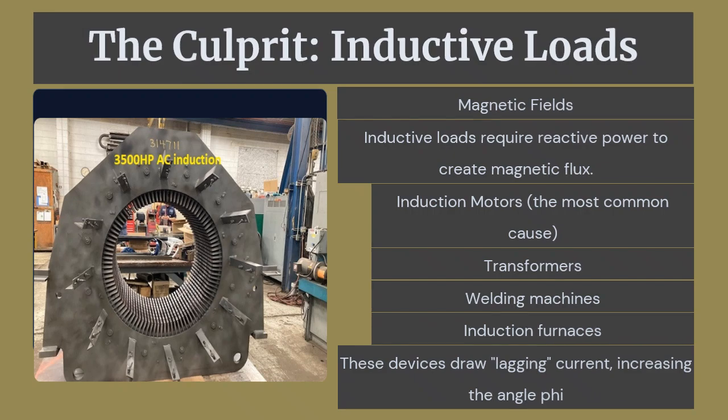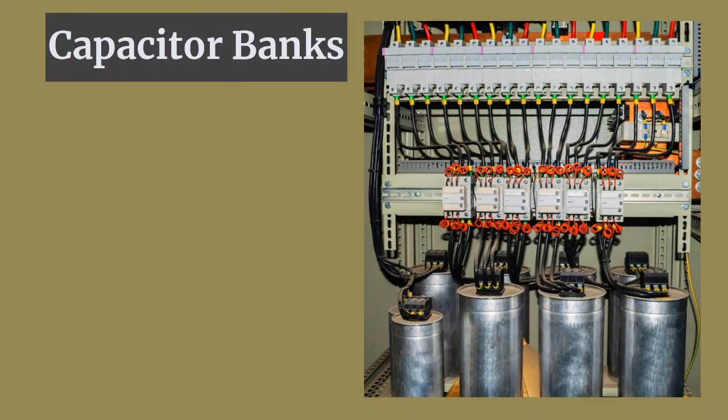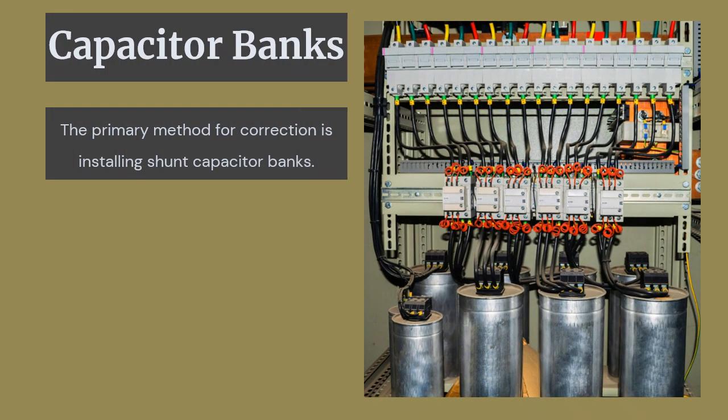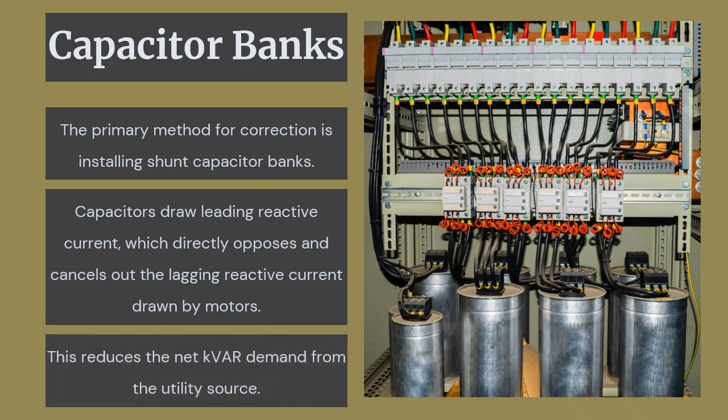Capacitor banks. The solution is the installation of shunt capacitor banks. While motors draw lagging reactive current, capacitors draw leading reactive current. By introducing a capacitor, we inject a current that directly opposes the inductive lag, neutralizing the reactive demand.